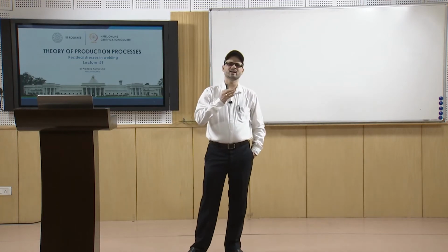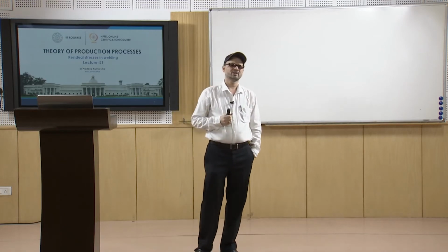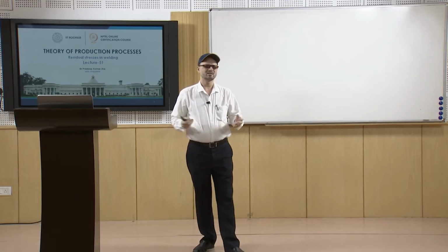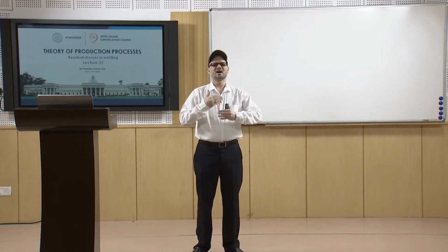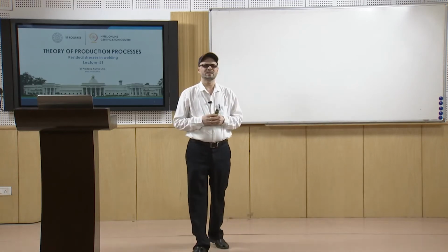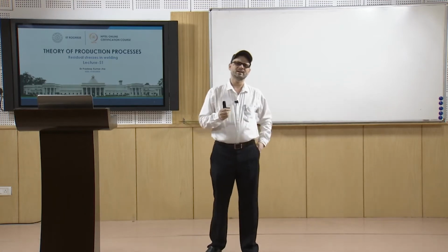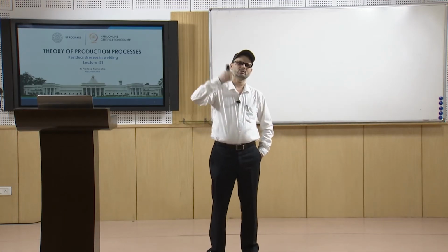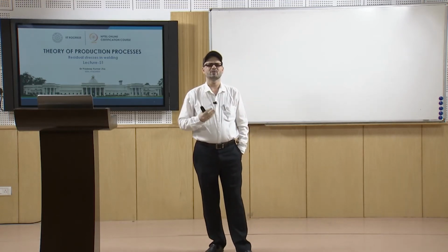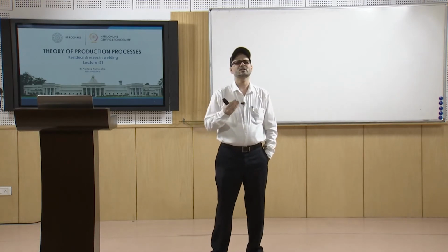and from there you have a very fast cooling rate because of the presence of metal all around. When we are doing the fusion welding of metallic plates, you have metallic plates on both sides, and you are also doing the welding by using filler metal. So, in the weld metal zone you have formation of a weld metal pool, that is in liquid state.